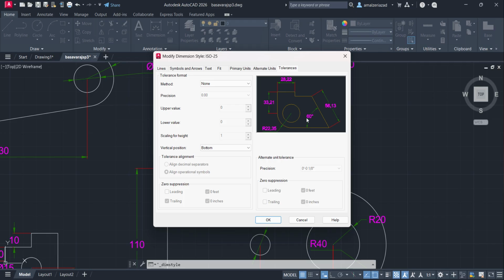So let's say you are creating a table in which you want to drill a hole with a drill bit. I have a 10 mm bolt which I want to fit, and I want a tight fit. In that case, you keep the lower limit of the tolerance, usually a 9.8 hole. If you drill that, it is fine, because with sandpaper or something you can sand it, add that bolt, and get the proper fit, right? Such things we will do. That is what is called tolerance basically.